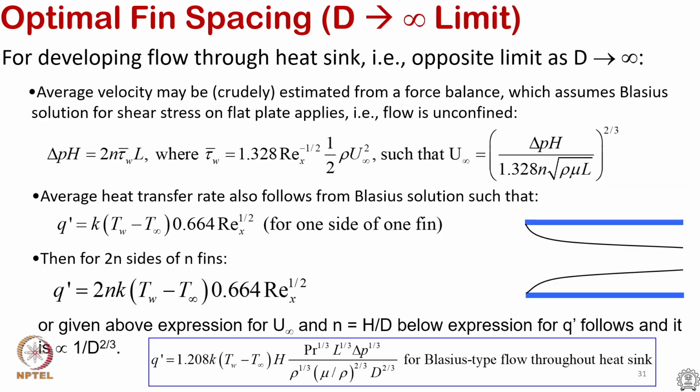Here one has to understand that now we are talking about internal flow, and for the sake of crude approximation we are ignoring the flow acceleration effects. We are thinking that the plates are so far apart there is no flow acceleration effect at the core, and we see only an isolated boundary layer developing and never merging before the exit of the heat sink.